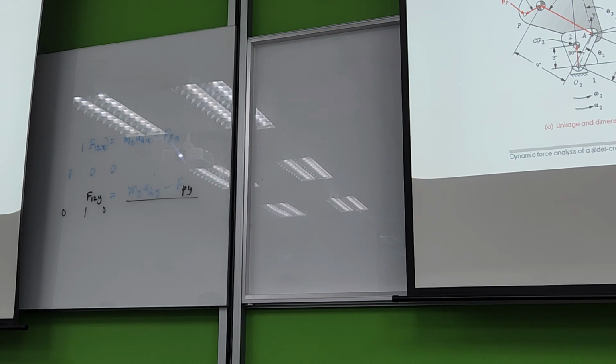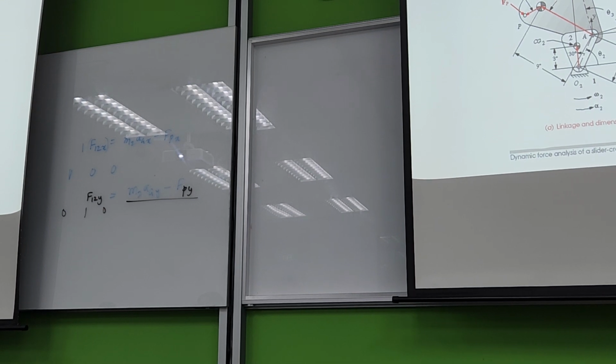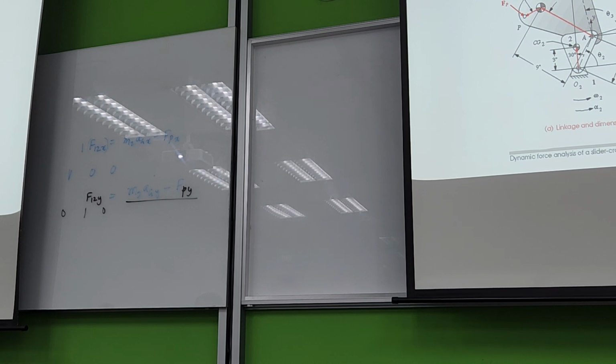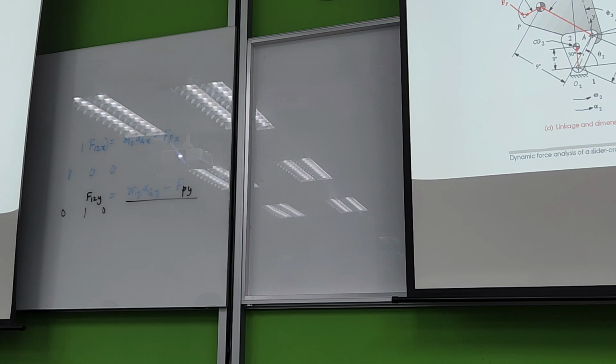Now this is basically a 3-bar linkage mechanism. So you have link 1, link 2, link 3. Slider is link 4. So this is also ground. So basically there is no slider here. So for the ground link, the free body diagram is F21 is equal to negative of F12. Now link 2 is very similar to what we have done. You can say link 2 is not a rectangular link, but a ternary link, a triangle shaped link. Now the centroid is given here. So you know the centroid, you know the dimensions.